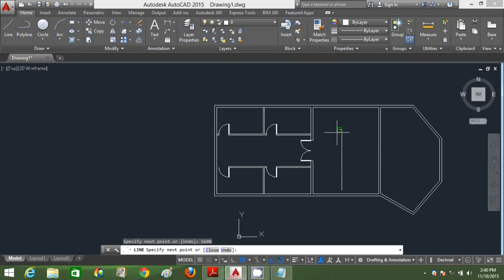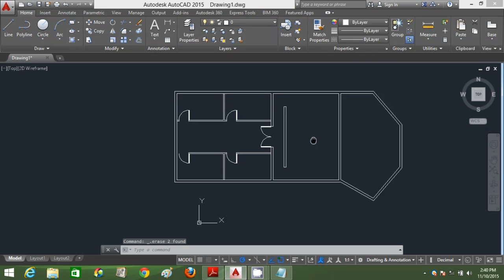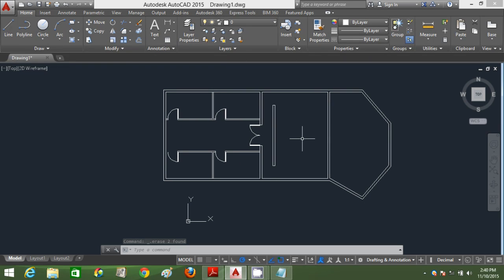Okay, for the reception, using the dimensions stated on the floor plan layout. Alright, so I'm just gonna draw it first, then move it later to centralize it. So I'm just drawing my reference lines first by 1000 mm and move the backdrop wall there. After that, I can delete all the reference lines. Alright, I've created the backdrop wall.